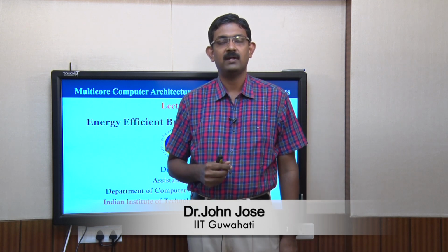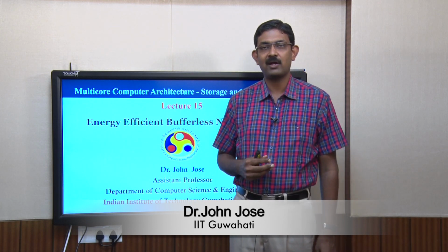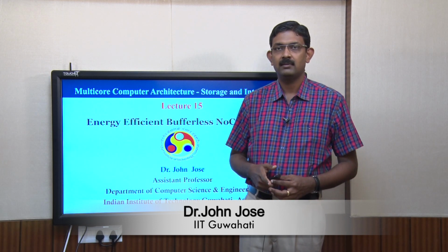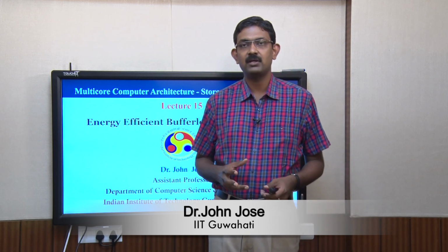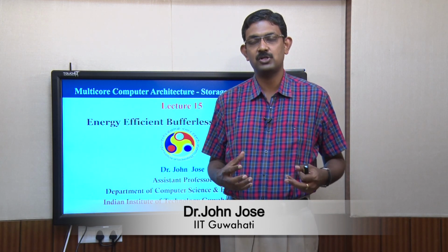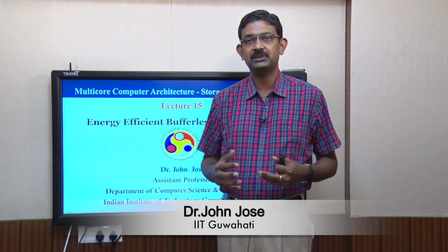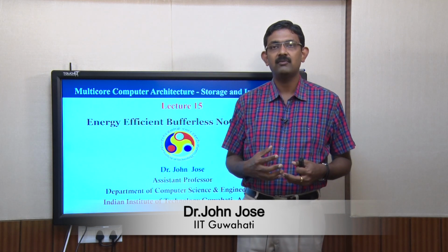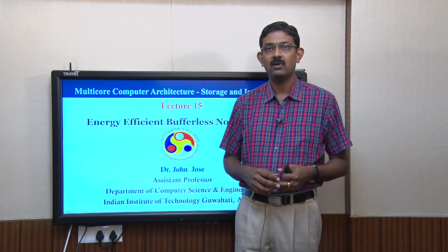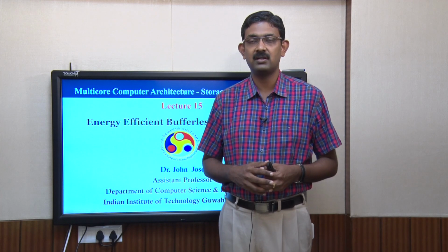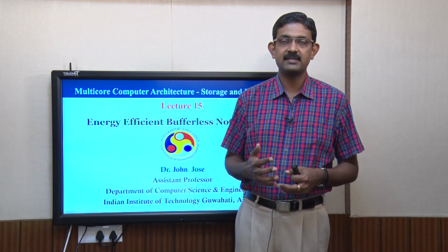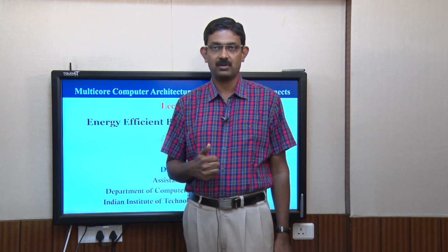Today we are going to see a special category of NoC router microarchitectures. So far we have seen NoC routers with input buffers, and buffers are going to consume power. Our discussion today is, can we have an alternative router design where we could eliminate buffers? So, the next two lectures are basically on the design of energy efficient NoC routers. This lecture is on bufferless NoC routers, and the next lecture is on minimally buffered NoC routers.